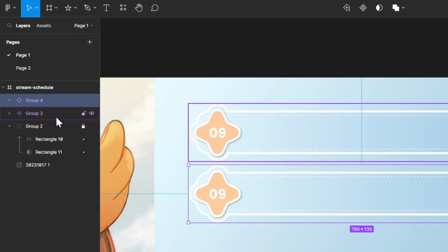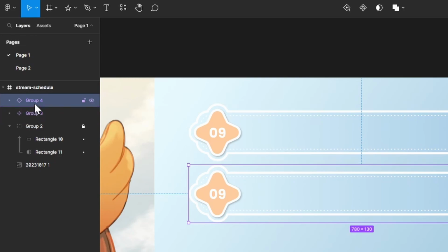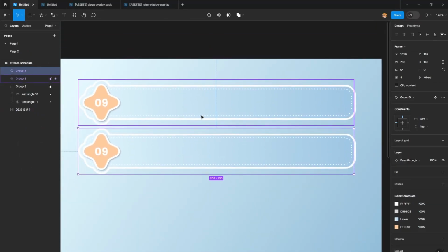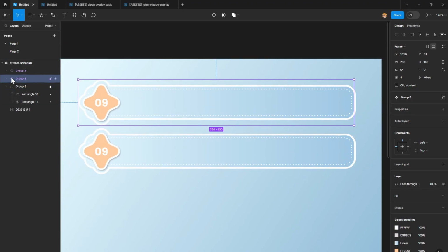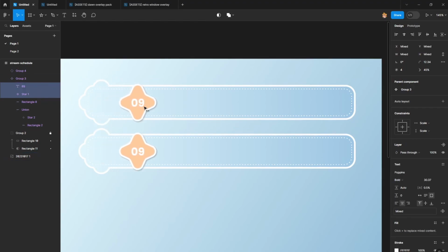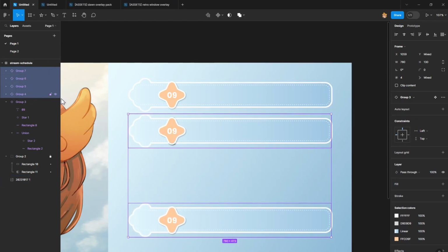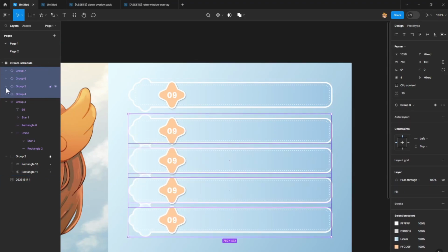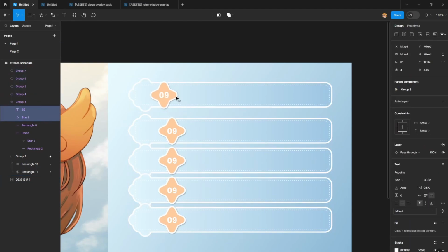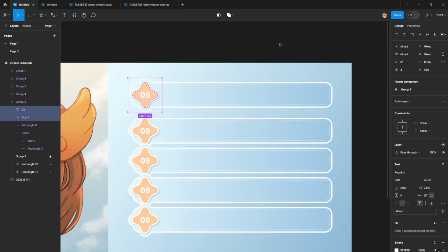The main component has a filled in purple diamond icon, and the duplicate of it has a hollow purple diamond icon. And you'll notice that any change that I make to this main component will apply to the copy of it. So for example, I'll move this star to the right. Every component will imitate that. So no matter how many I make, I can keep making more and more of these guys. They will continue to reapply whatever change I make onto the main component.